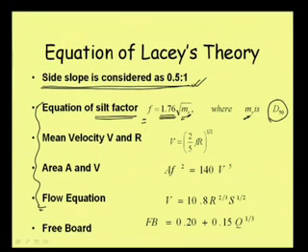Then we should carry out sieve analysis, and see the size of the sieve through which 50% finer we are getting, and that we should consider as the D50. That D50 value we should put here as a representative value of silt factor F. Otherwise, silt will be of different sizes definitely, and we need a definite value. So, that definite value we are getting by this approach.